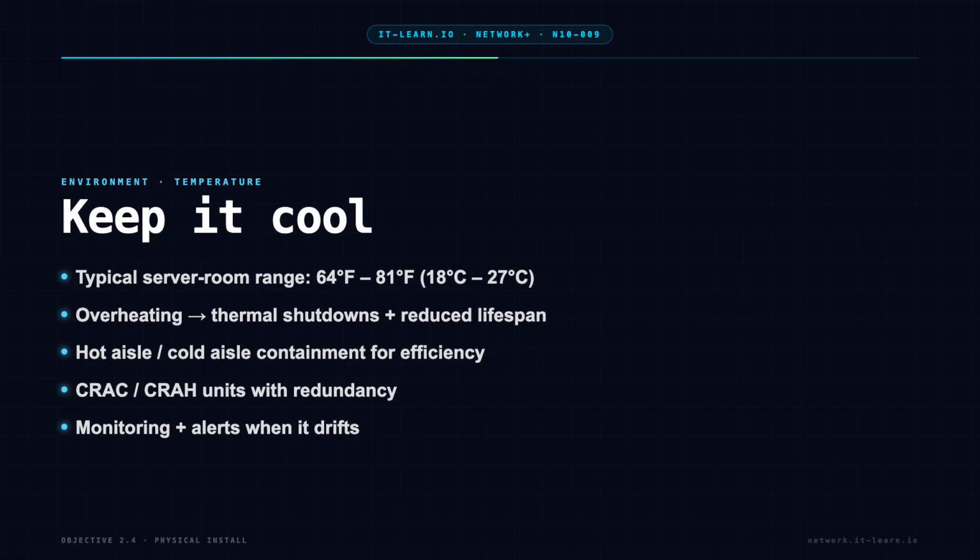Data centers and server rooms require dedicated cooling systems. Hot aisle and cold aisle configurations are used in data centers to optimize cooling efficiency. Cold air is directed toward the front of equipment, and hot exhaust air is contained and removed.